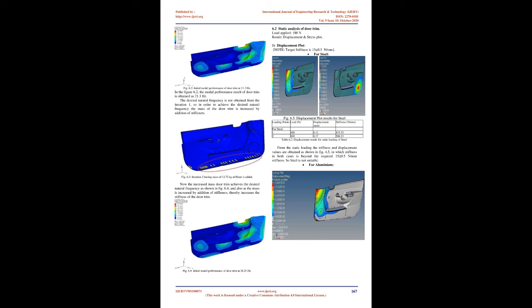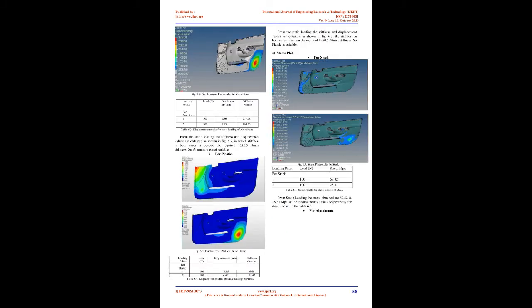Note, SPC means single point constraint, which is provided with rigid element RBE2. A single point constraint is given to a node that will be fixed in one or more DOF. The value may be 0 or non-zero. Outside the step we use the non-zero value, while zero SPC can be called both outside and inside the step. The word SPC can be used in any software boundary. There are 6 degrees of freedom in total: 1 equals translation in X, 2 equals translation in Y, 3 equals translation in Z, 4 equals rotation about X, 5 equals rotation about Y, 6 equals rotation about Z. The rotational degrees of freedom can be applied to beam and shell elements only.